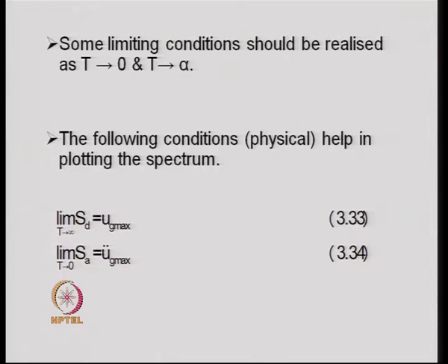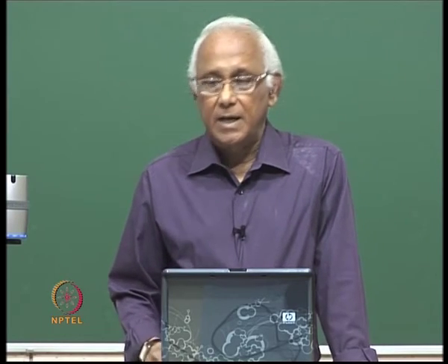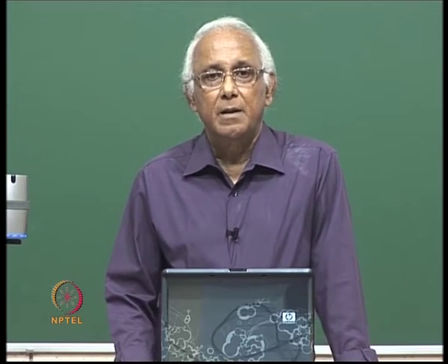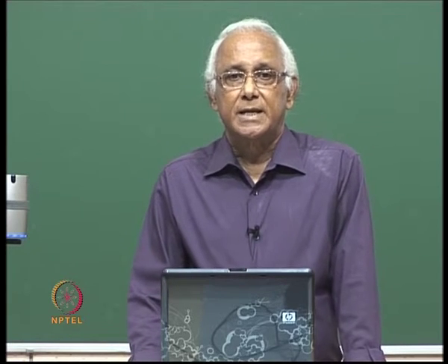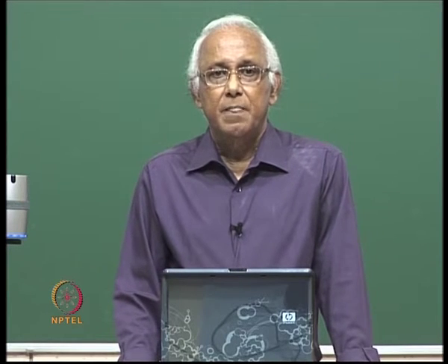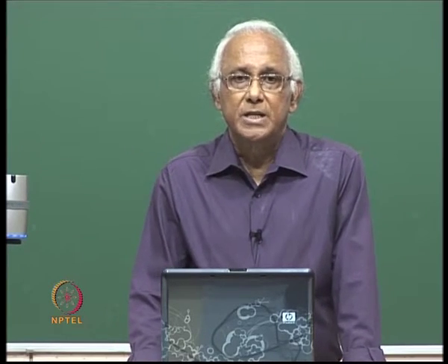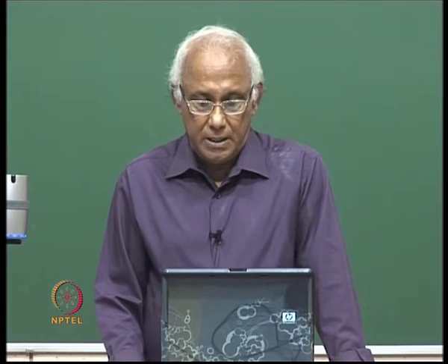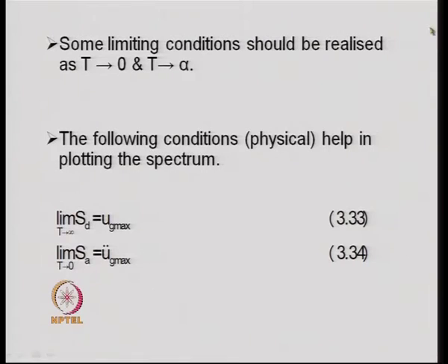One is the horizontal axis in the log scale, other is a vertical axis in the log scale, and two other scales, which will be inclined lines perpendicular to each other and also defined in a log scale. Now, these four axes define the quantities, that is SV, SD and SA for a given omega n value.